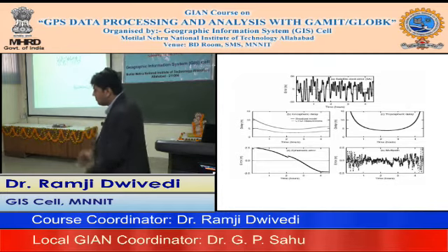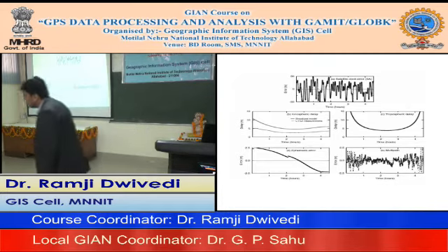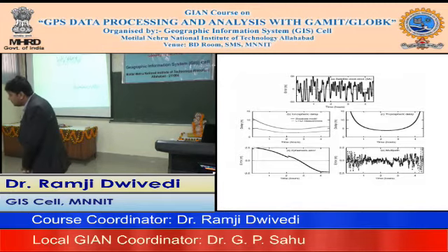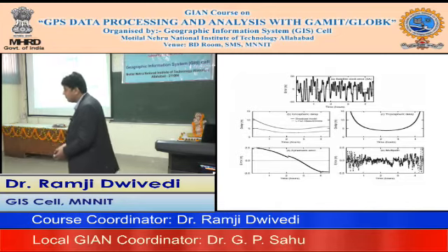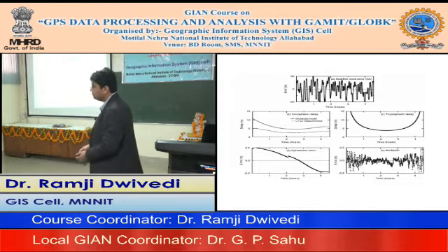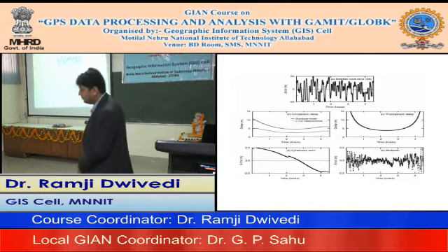Yeah, the full model they use is quite complicated, and so they have a very limited amount of space they can transmit it in. At 50 bits per second, think about what your current gigabit internet rate is, 50 bits per second is a very low rate. So they have to make it a simplified version to get it into the message format. And so inside the satellite, it recomputes those numbers every 2 hours to get a better representation of the more complicated model that's being uploaded.